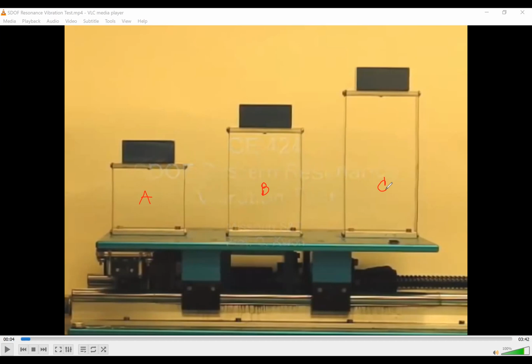For sure, if the columns are thin steel plates with the same width, you can imagine that building C has longer columns, right? Therefore the stiffness of the column depends on its length, 1 over length to the power of maybe 3. What does it mean? It means that building C has smaller stiffness than building B, and building B has smaller stiffness than building A.